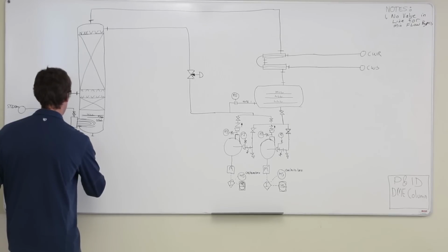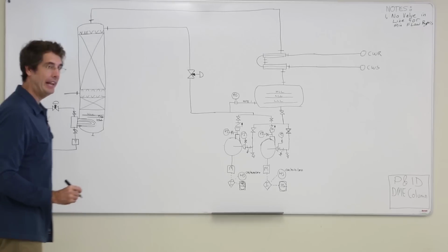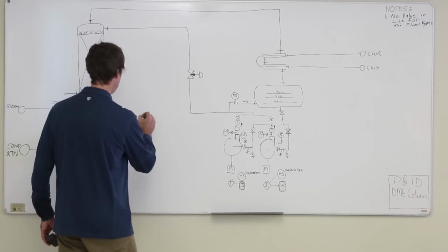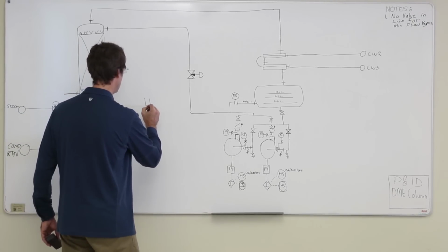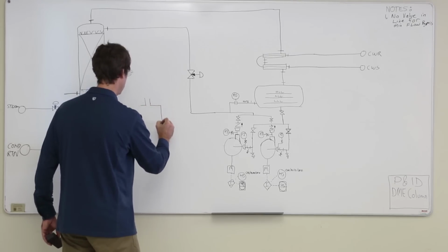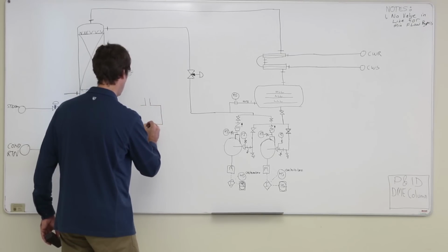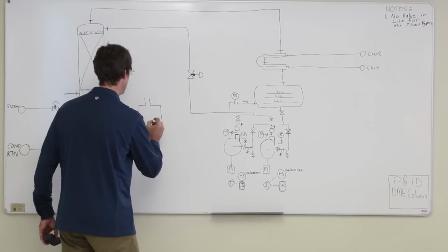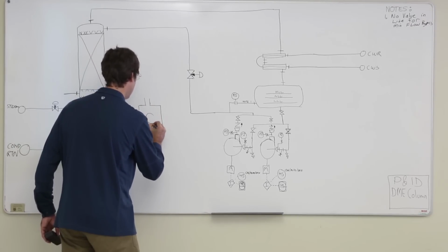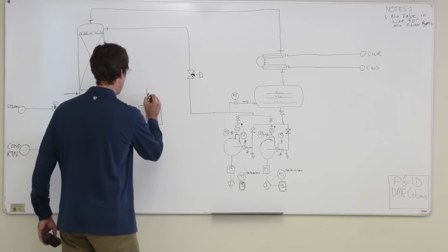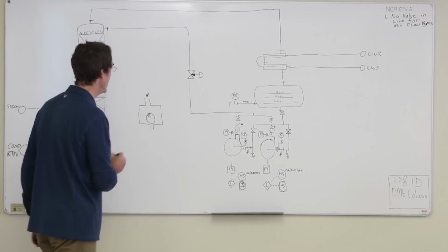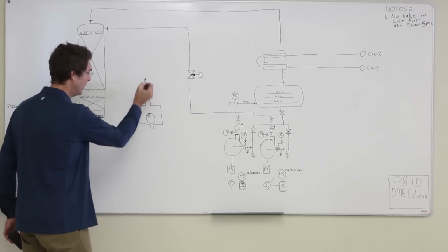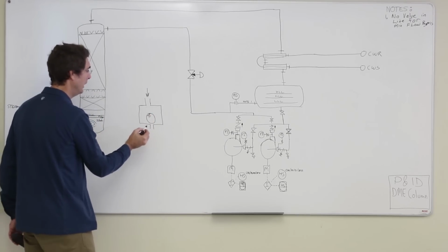If you don't know what a steam trap is, there's a bunch around the ILC, a lot of them. The easy way to think of a steam trap is a box that's got a ping pong ball in it. There are all sorts of different types, but this is just an easy way to think about it. Coming from the heat exchanger, there's water and steam coming down through here.